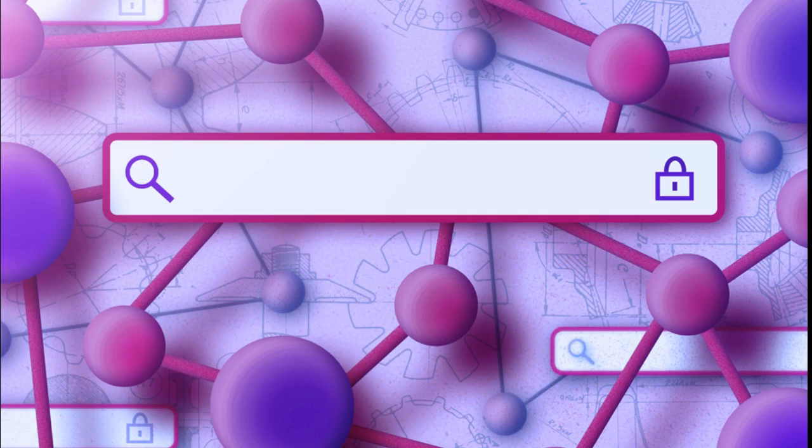Then authentication cuts the data into uniform chunks and assigns a cryptographic hash to each chunk of data, which is stored along with the data chunk in off-chip memory. When the accelerator fetches an encrypted chunk of data known as an authentication block, it uses a secret key to recover and verify the original data before processing it.